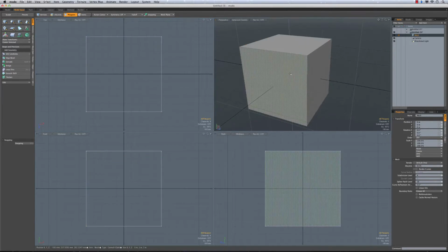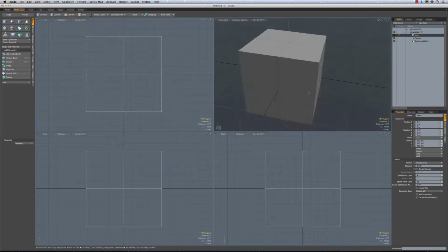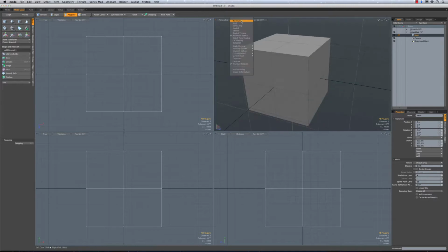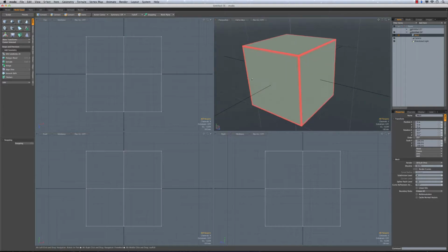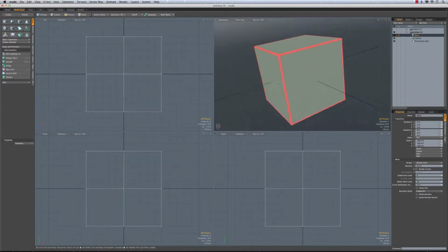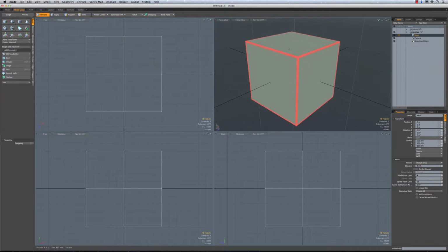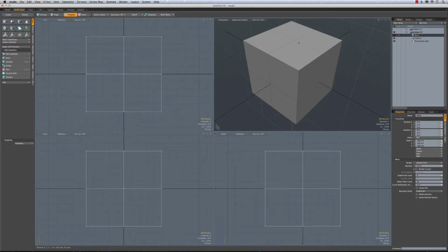So let's go ahead and press Shift D to add just one level of subdivision into here. And now if I were to look at this, my vertex map has sharp all around the corners and then empty or no sharpness on these faces. All right, so this would allow you, actually, let's go back to advanced OpenGL. This would allow you some interesting things if you want to move some of these vertices.